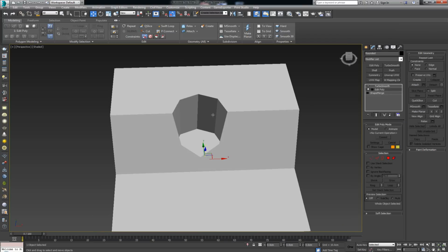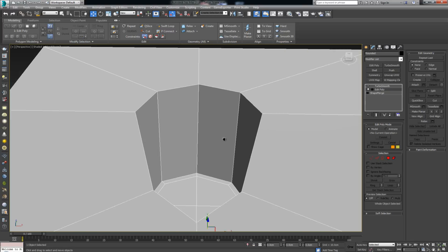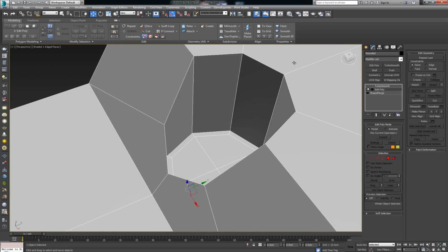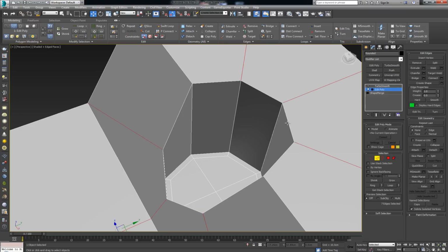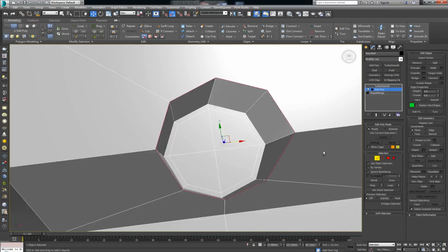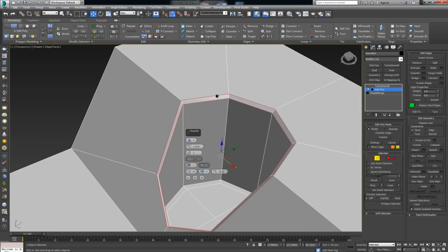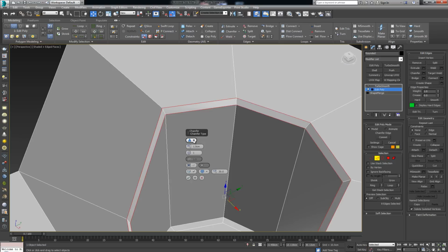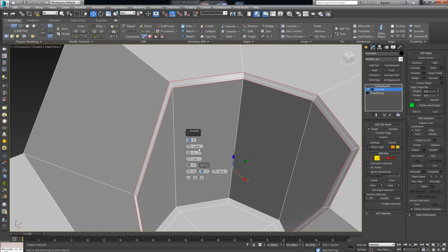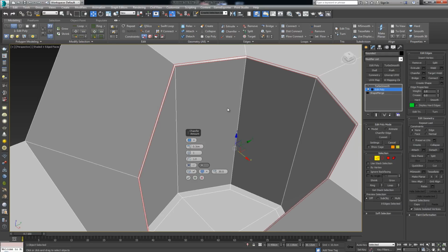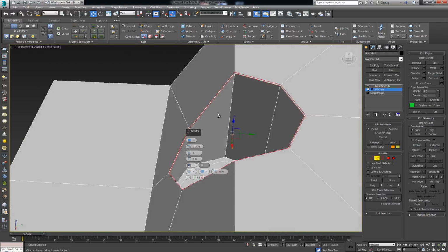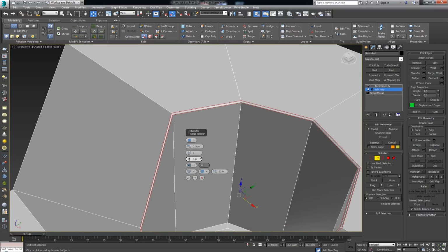And that can be done with the two ways that I previously showed you. We can either fence this in, or I can use the chamfer option. So let's try it with chamfer this time. I'm going to go ahead and chamfer this, make sure it's in quad, and put in a smaller amount, something like 0.3. Yeah, this should hold the form much better. And here, I'm just going to put the edge tension to 0.5.